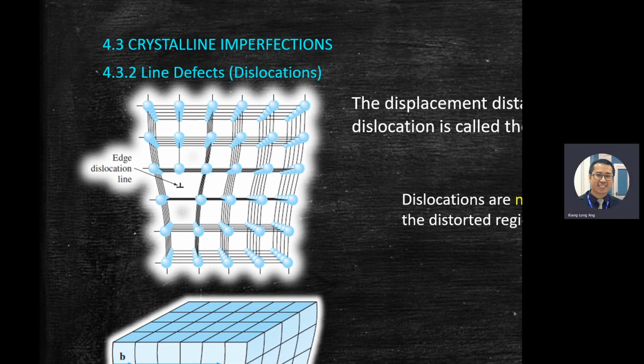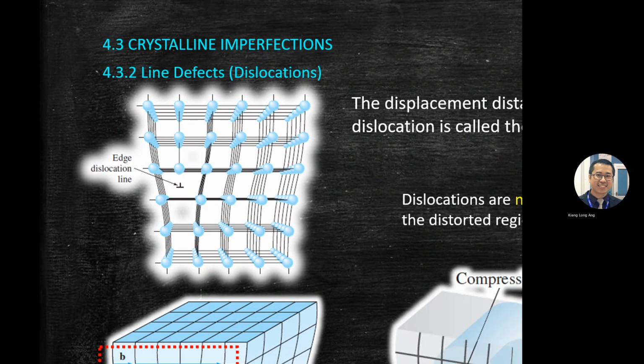This type of dislocation is a non-equilibrium defect. Non-equilibrium means the force is not the same around the atom site, and they store energy in the distorted region of the lattice around the dislocation. So if there is a missing atom, there will be a tension and compression site. Right? There will be a tension and compression site.